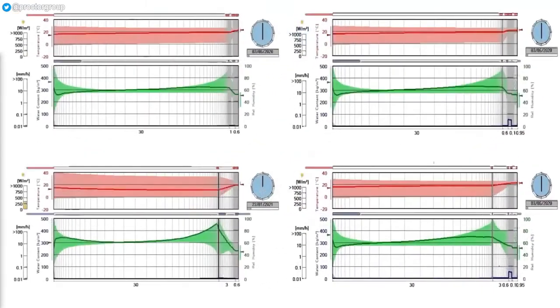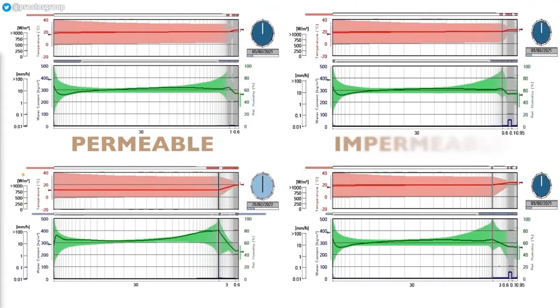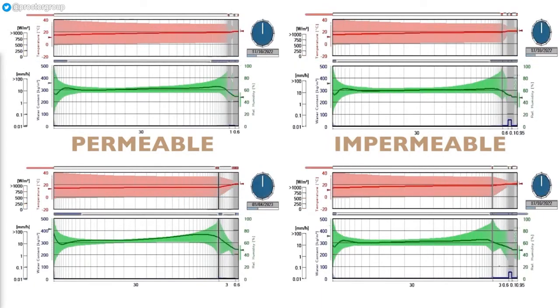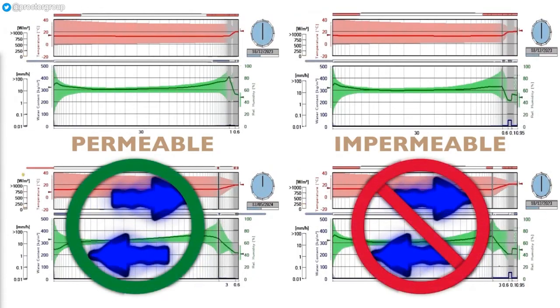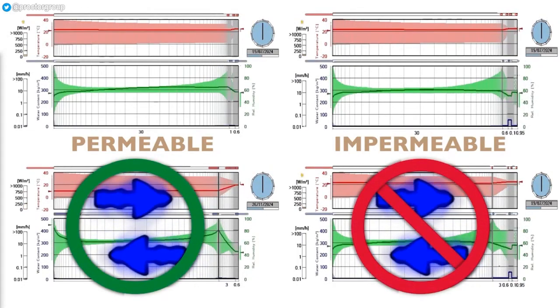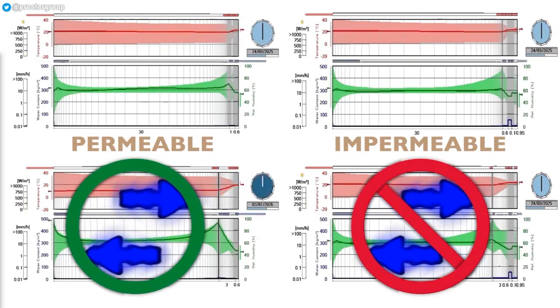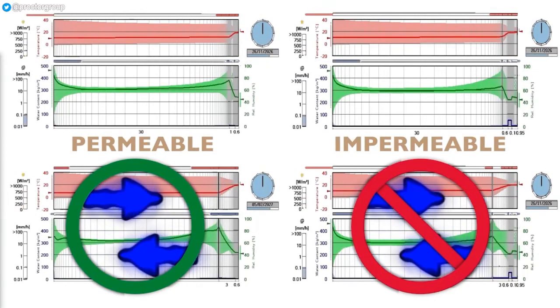As can be clearly seen, the permeability of the Spacetherm multi-boards allows for a greater drying out of the construction, as this is possible to both the interior and the exterior of the building. This results in much greater swings in the value of the relative humidity, but the values are lower overall than when the vapour checking Spacetherm wallboard is used. If we then look at the water content of the stonework, this can also be seen to be lower when thinner and more permeable insulation is used.